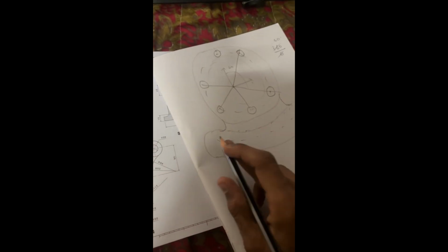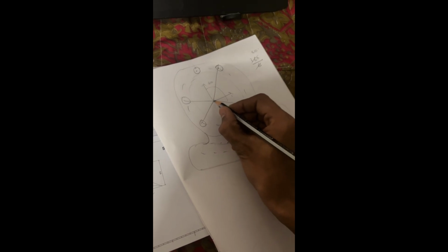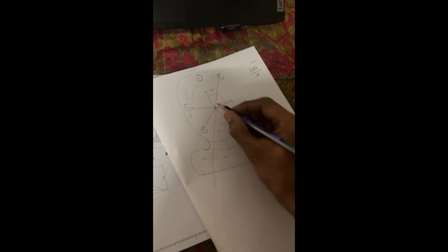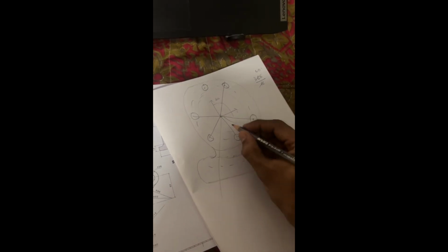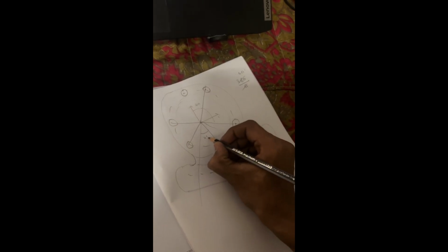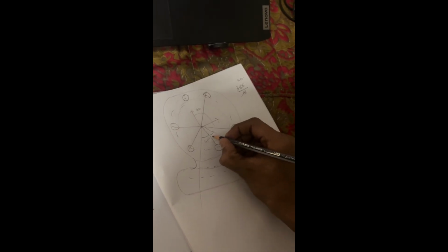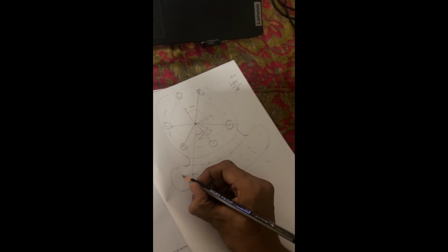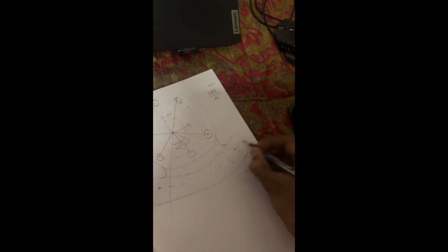And to constrain this keyhole, we need to draw 2 axis lines like this, which are 45 degrees from the center line. 45 degrees, and this line is to be constrained with the center point of this arc and this arc respectively. By constraining this and providing the radiuses, the first sketch can be drawn easily.